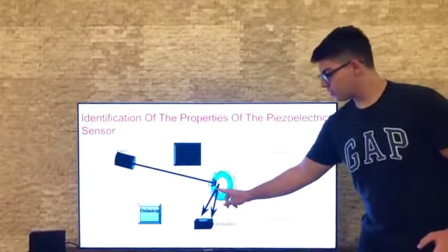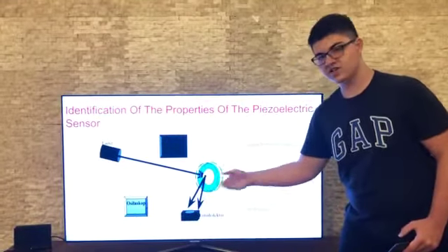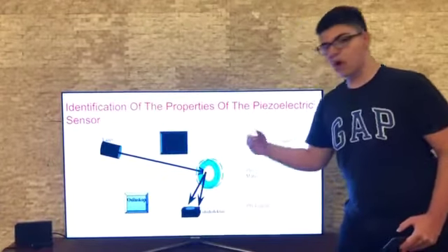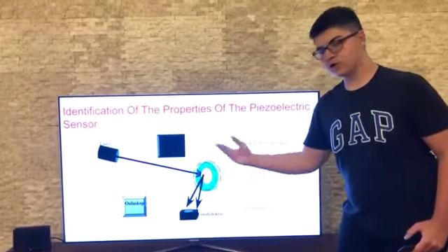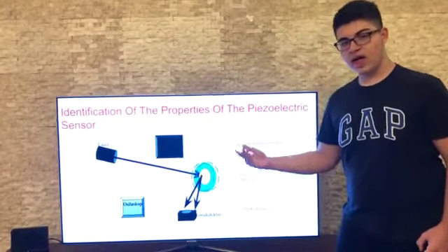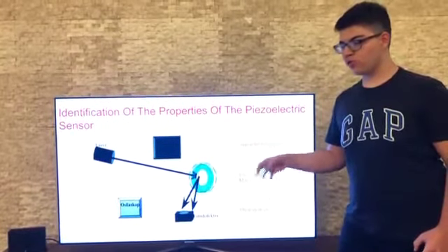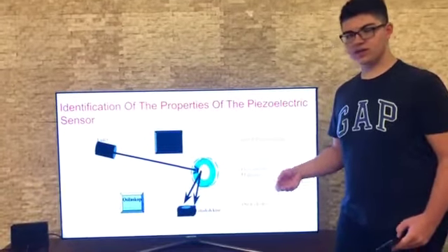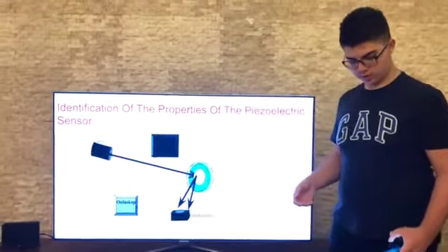With this movement, the laser reflected from the piezoelectric sensor also changes its angle, and we can measure that change with the photodetector. Where the most change occurs is where the piezoelectric sensor vibrates the most, and thus we can find the resonance frequency, which we used for the frequency of the light we sent to the sample. And we measured that frequency as 3 kHz.